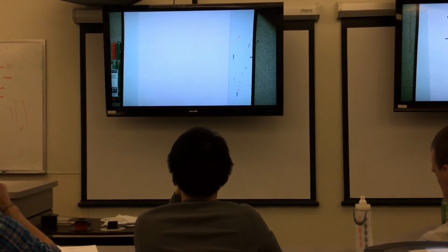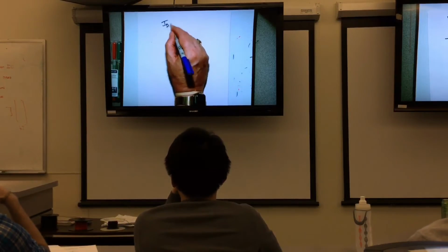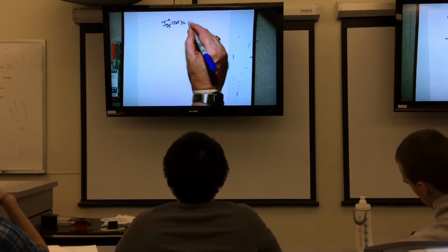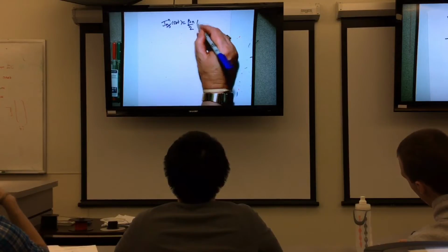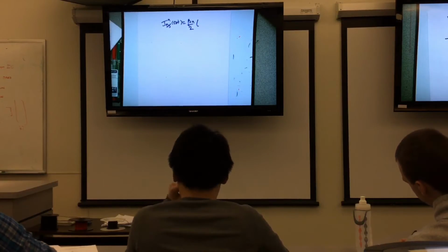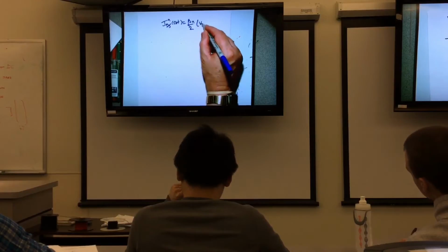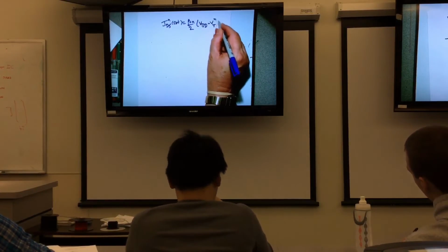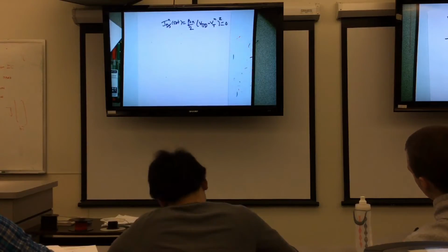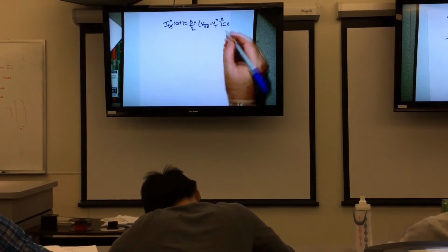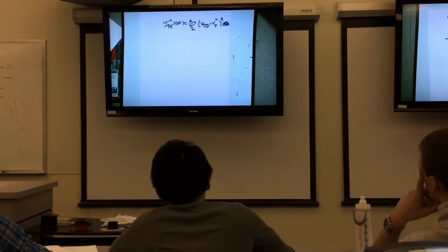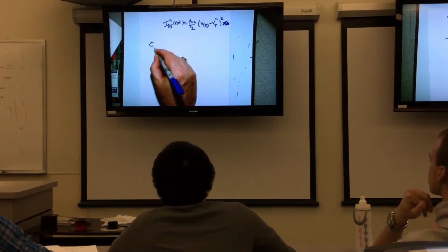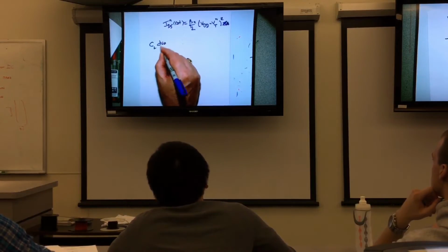Okay. So IDS in the saturation region is going to be beta n over 2 times, and the assumed or presumed input voltage is going to be a full VDD. Probably isn't that in the real world, but we make it so for the purpose of analysis. So that's our equation for IDS sat, which means our differential equation is now this.